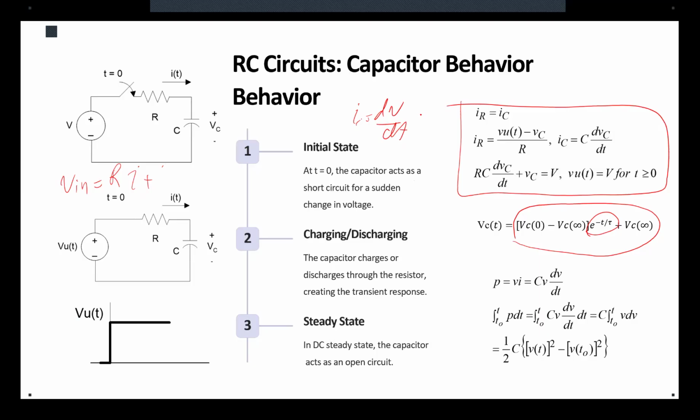So what is the voltage? It's going to be the integral of the current. Very good. So we are going to have 1 over C integral. This is C dV over dt, so if you reverse that, it's going to be 1 over C, the integral of the current, dt. Are we good? We don't like the integral, so we take a derivative of our equation.